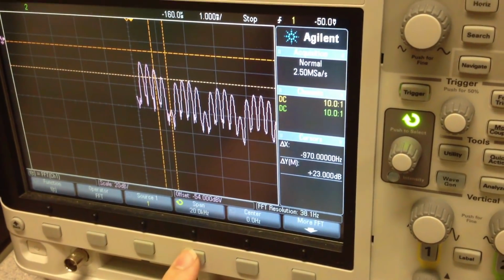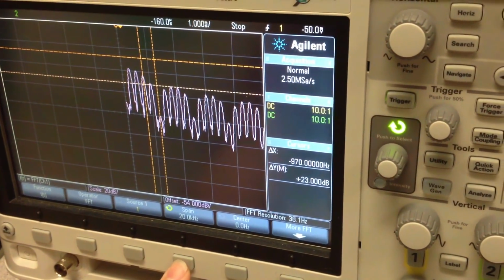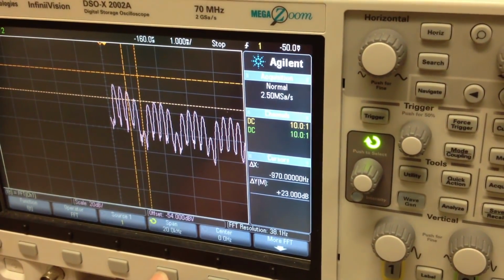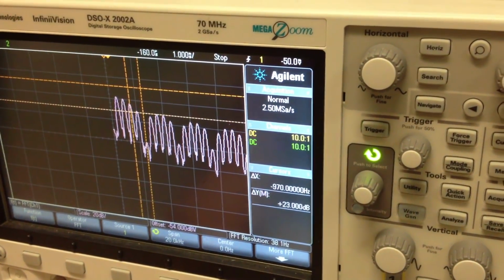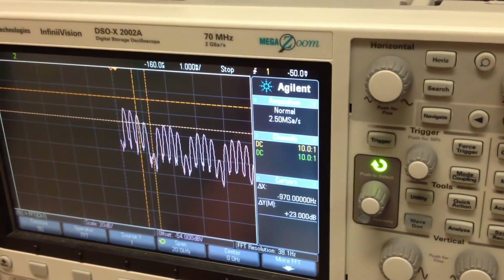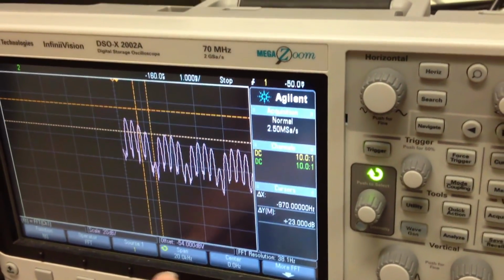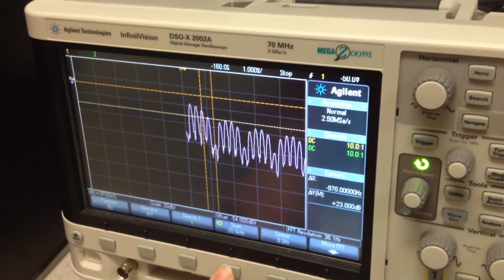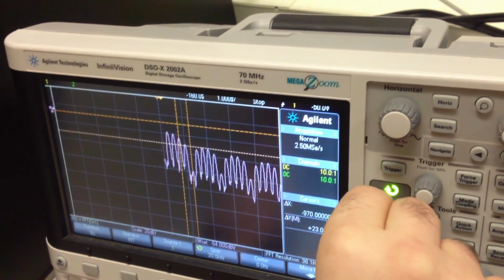This is the span of the signal. Our fundamental frequency is 500 Hertz or 0.5 kilohertz, so it will repeat every 0.5 kilohertz. So 20 Hertz is too many bins. We make it 10, for example.